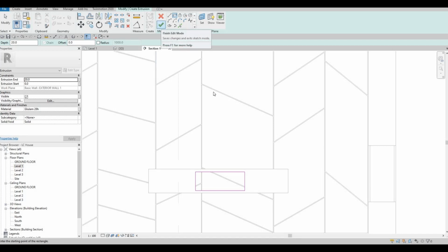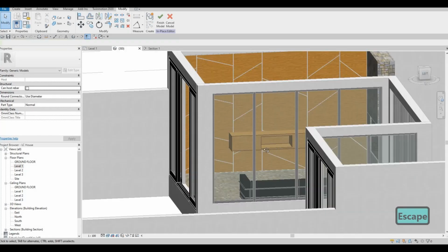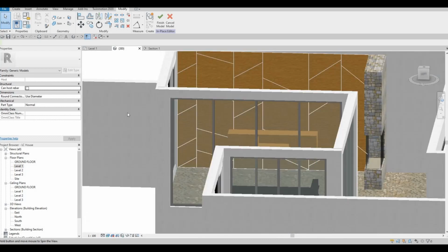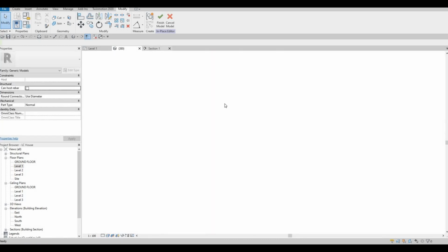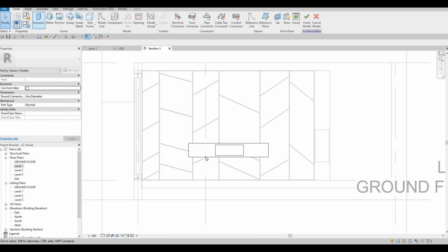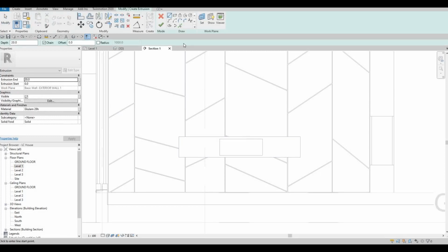So I'm putting it more over. So now it's not showing, but it's not big enough to be flickering. That's what flickering does, is if there's overlapping and they're in the same plane, it's gonna flicker and it doesn't look nice. So now here, we're gonna extrude something right here so that it looks much better.